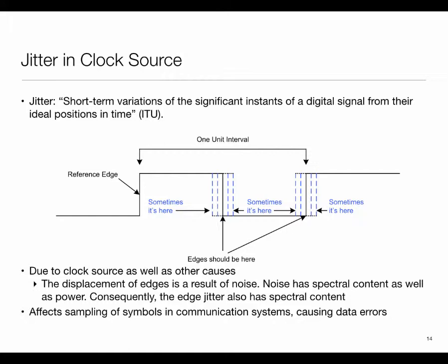A very good example is that there are a lot of these GPS devices, and we all know that GPS gives very good time. Indeed, it does. Inside the GPS receiver, they estimate time, which is pretty accurate down to tens of nanoseconds relative to the atomic clocks of the satellites. The problem is most of these GPSs expose their information through a serial port. Usually that's the most common way. On that serial port, there is a very well-defined protocol, essentially a set of characters which are sent out. So the serial port is basically a UART. Inside the UART are buffers, and there is highly variable delay.